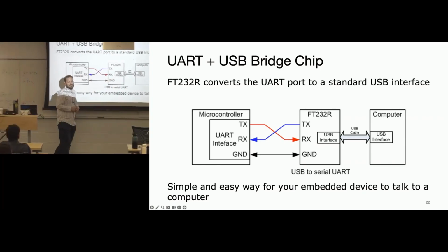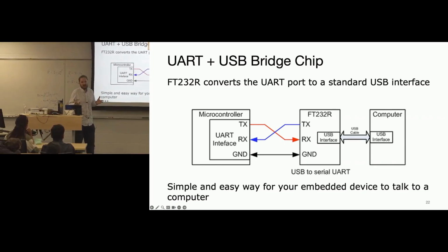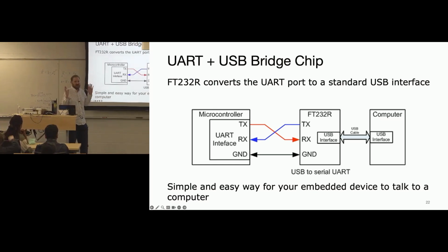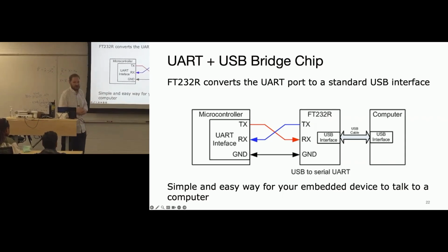And for your projects, that's really nice, because sometimes you want to debug. Like, why is my little robot always doing crazy things? Or like it's autonomous, it's trying to move around, and you don't want to have cables and be running after it with your laptop. We can just have it send diagnostic messages over Bluetooth saying, oh, I got a left command, I got a right command, this timer went off. Now you at least can figure out what the weird state of your device is. So that's a really useful tool for debugging, but also just for getting data on and off a device. Any questions?